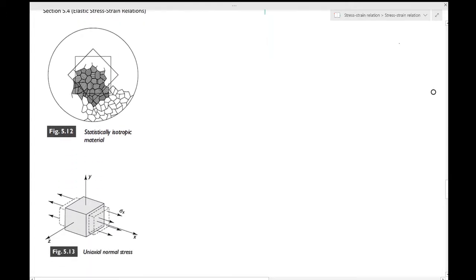So it's materials like, say, rubber. Okay, there is a large non-linear elastic strain present, so we cannot make that approximation over there. But for most other materials, linear elasticity works good enough if the strains are small. Even in materials like steel, if the strains are large, then we cannot assume linear elasticity, and we have seen the figure in this chapter itself. Okay, for larger strains there is no linearity.